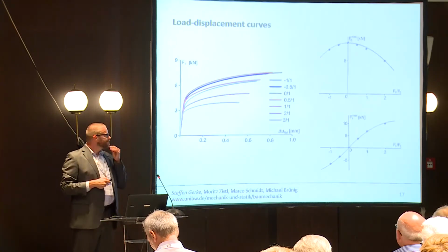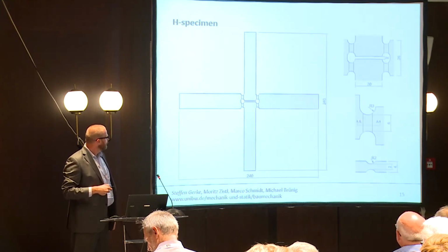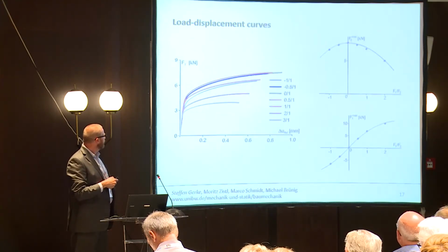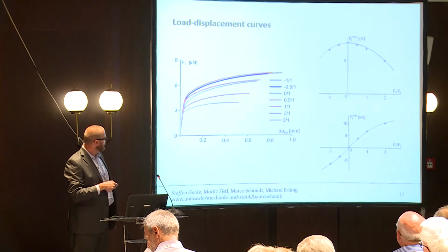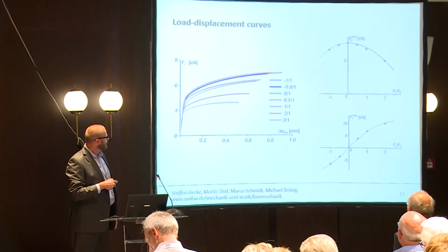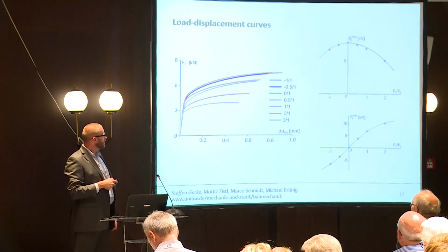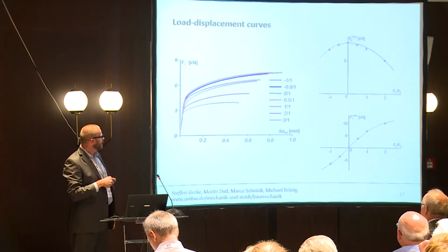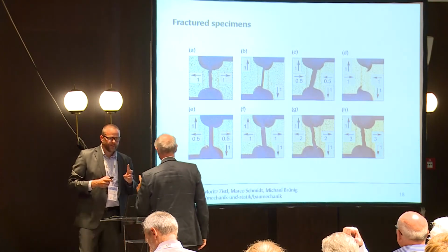Some global results. Here we see load displacement curves of this direction. So we have here a reduction of forces with ongoing tension or even with ongoing compression. We have buckling below -1 for the specimen. That is why only these load cases are presented here. Here you can see by the blue diamonds the experimental points, and the black line is maybe an approximation of it.